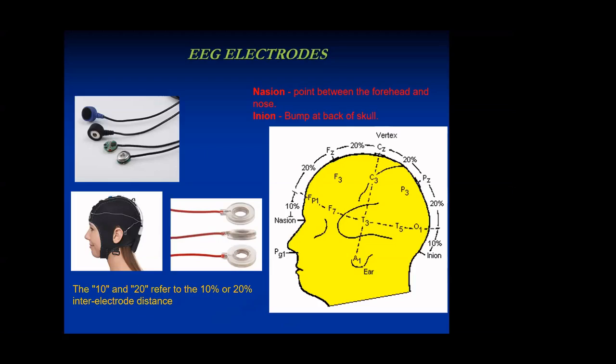potentials. But the problem with these electrical potentials is they are very weak. The amplitude is of the order of microvolts, which we cannot process unless we amplify, and they will be buried in noise. So you have to remove the noise before applying to the analog to digital converter. These operations you can do using digital signal processing also. Basically in digital signal processing also we are going to do the filtering only.